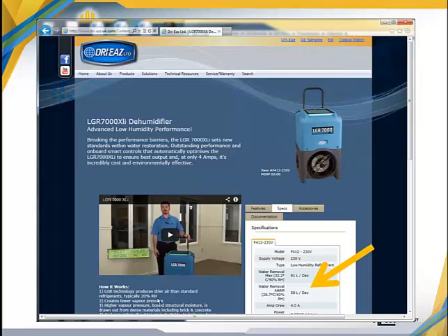However, as a restoration contractor, you should never allow an environment to be above 60% relative humidity for any substantial period of time. In other words, you'll never realize 91 liters a day. And if you do, it's because you have an extremely humid environment that is suffering secondary damage. This is not a drying environment, that is a wetting environment. So the realistic number is the AHAM number, and the calculations we just reviewed are based on that AHAM number.